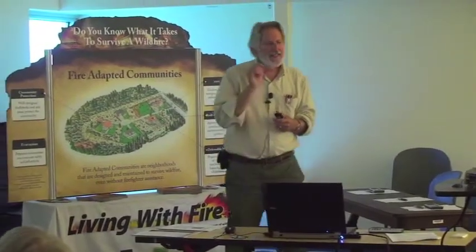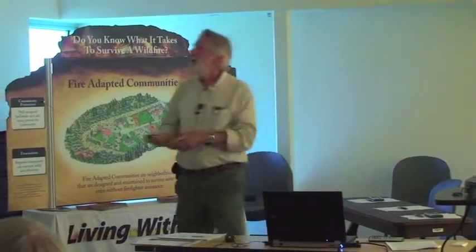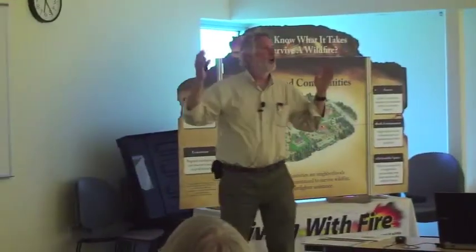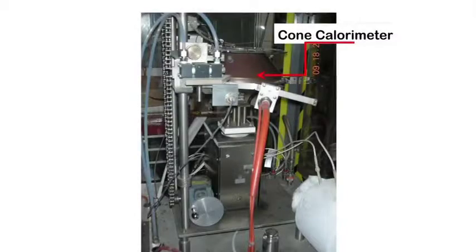Okay, and then if you have a tinier thing, under this hood, this is for a larger. You can put components, you can put outside, you can have a large deck underneath this hood. If you have a piece of that deck or a piece of the siding, then you can measure the same thing, the same heat release rate, in this thing called a cone calorimeter.